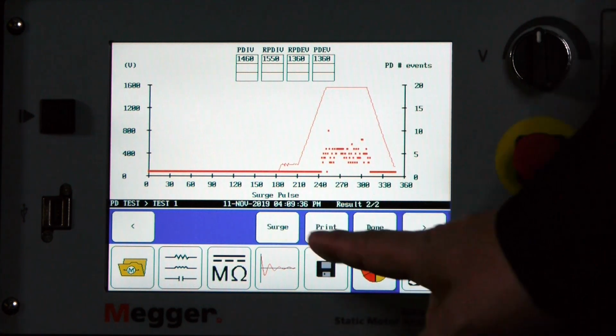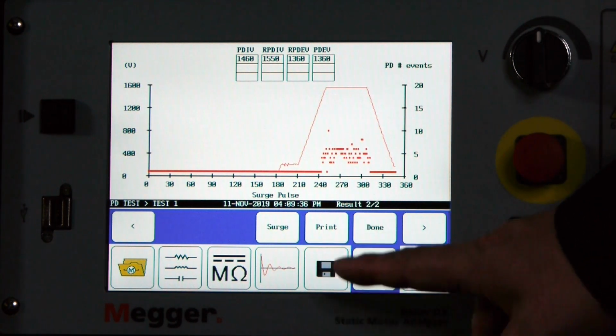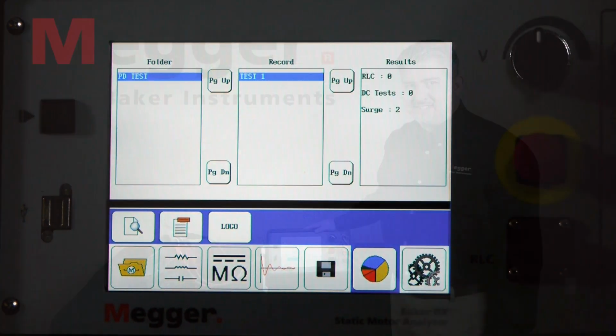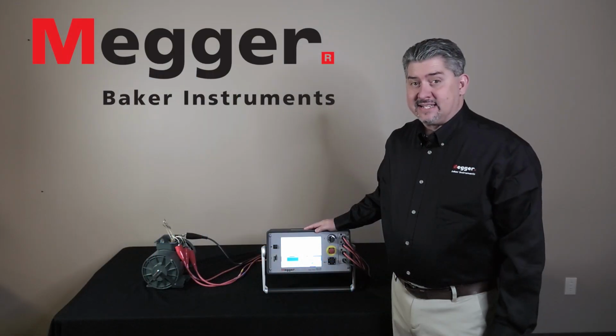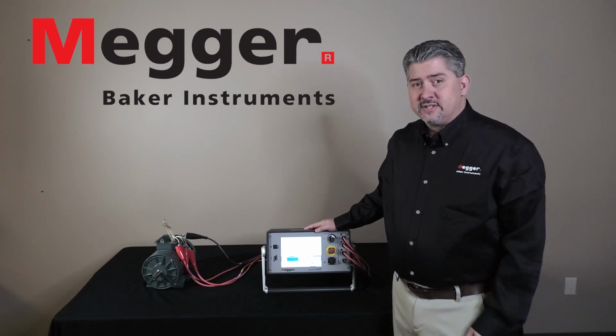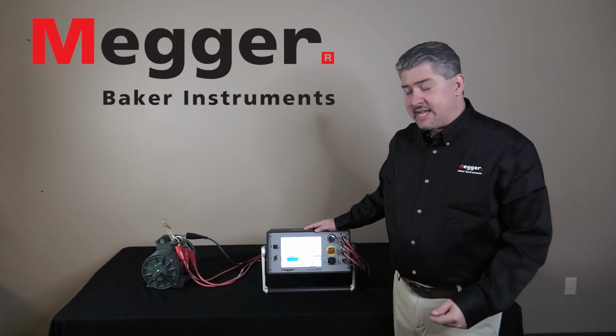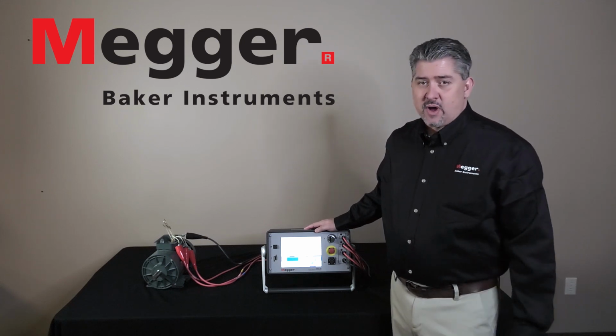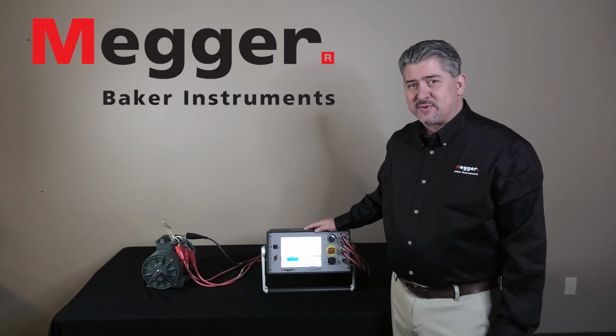So that's pretty much it. You can print that out from your DX, or you can export that data and use it with your Surveyor DX software. Now we can see how easy it is to detect partial discharge in your motors. For either manufacturing or for predictive maintenance, the Baker DX, equipped with the optional PD module, will show you the condition and quality of your motor windings.